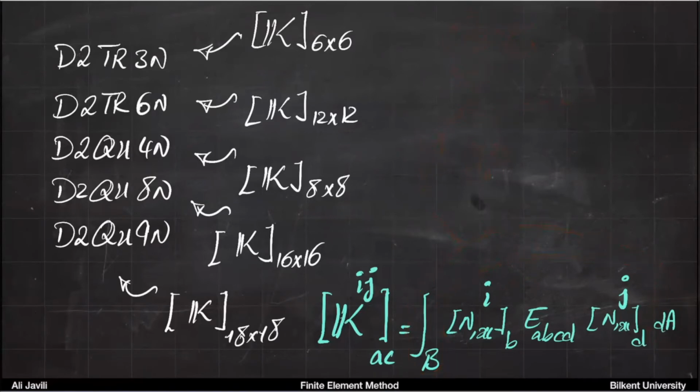But then there are still two problems. One is, what are these guys? So these are the derivatives of shape functions. Now, these are the derivatives in a physical space, okay? Which tells you eventually what you have here is a function of X. It's a function of your physical space, right? So this is not suitable for integration. Okay, so that is problem number 2.